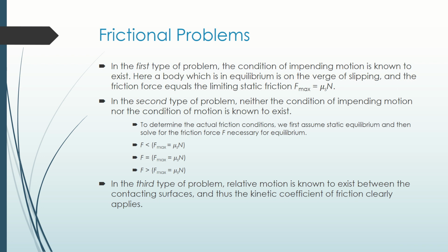Now if F is greater than F max, then you have to understand that the object is in motion and mu s is no longer going to be applied. In fact, you have to calculate for mu k.